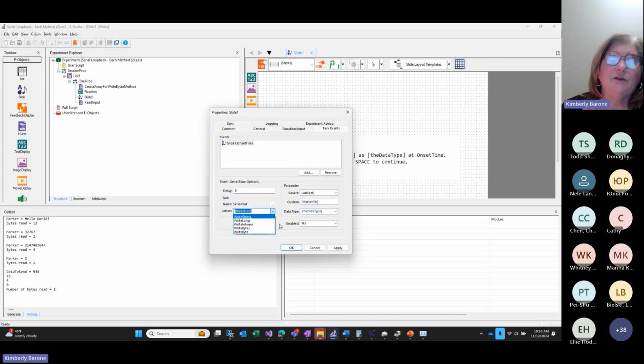Again, for example, if you needed to send a command like stop or start to an external device, you may need to send a string value over the serial port. However, you can also send numbers. You can send a long value, an integer value, or a single byte, which, if you remember from earlier, represents 8 bits. Or there's a variety of devices that require an array of bytes to be sent. The trigger box is one of those devices that requires a write bytes. You can call that to set a series of bytes to be written out. So again, the actions are specific to the device.